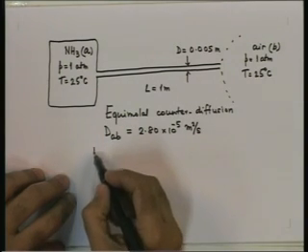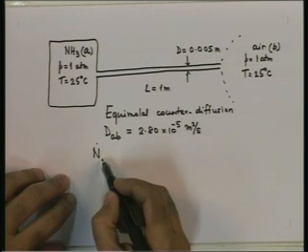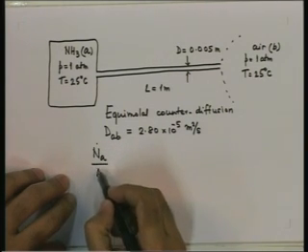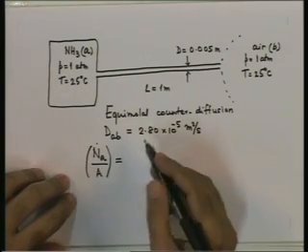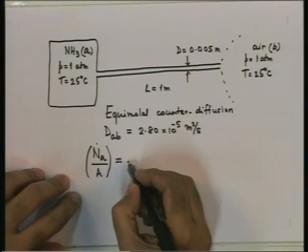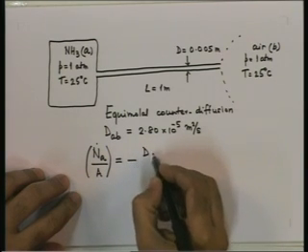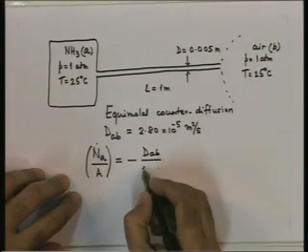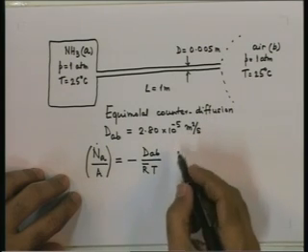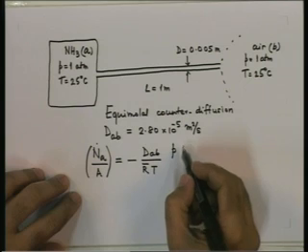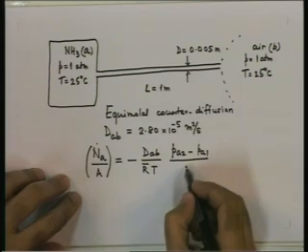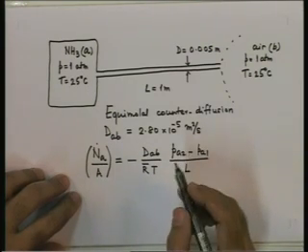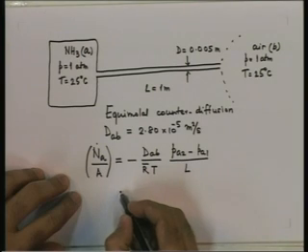And we have an expression for the molar flux of component A, in this case ammonia. Because it is a process of equimolar counter diffusion, this will be minus DAB divided by R bar T times PA2 minus PA1 by L. Let us substitute.